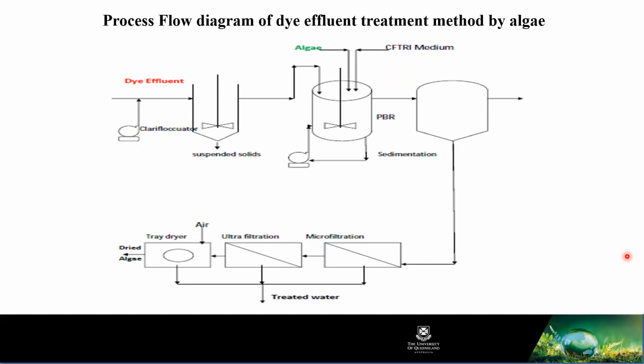So the secondary treated dye effluent was sent into the clariflocculator and then into a photobioreactor. He wanted to control the contamination in that. Therefore, he went into a closed system with artificial light, which gives more light energy instead of sunlight, and also a controlled environment full of glass. It's pretty hard for other contaminants to grow and cause problems. Then it goes to sedimentation, where he added the flocculant to remove the algae, and the remaining supernatant water goes out and is used in different processes.